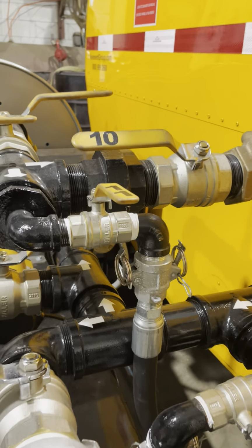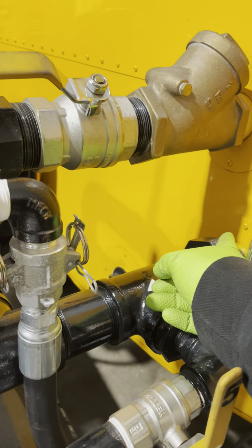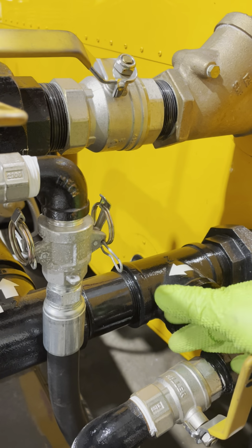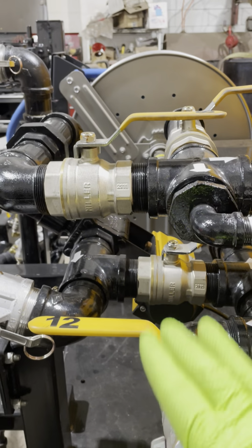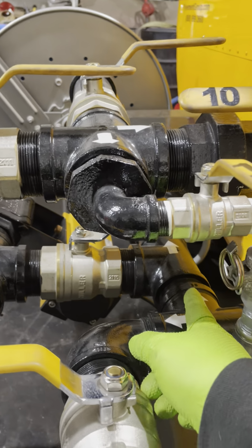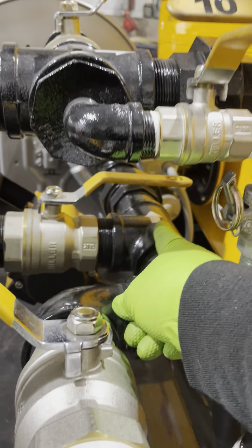Moving on, we're going to continue to flush out the manifold. We still got solvent coming in from the front. We've capped it off here. It's not going there anymore. It's going to follow this way. It's not coming out here. This is the discharge. It's going this way. We want to flush out our spray bar as well.